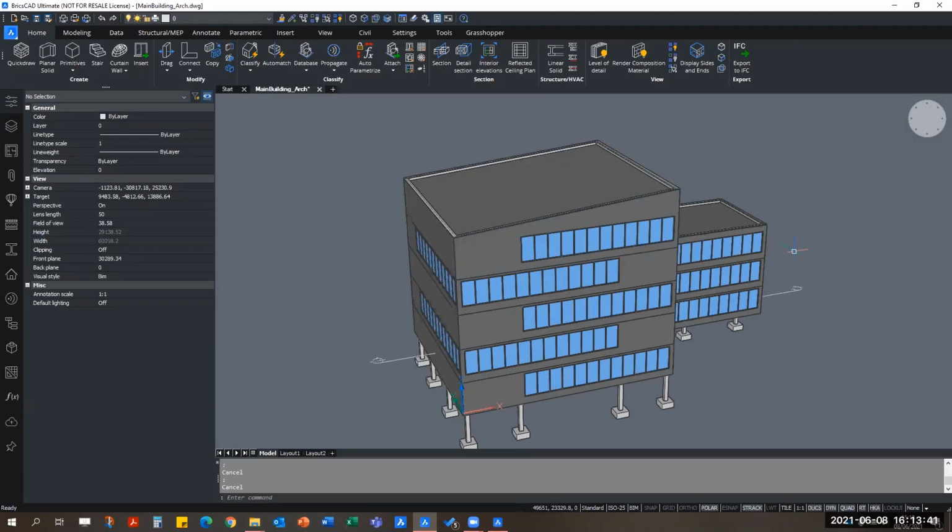Whilst this may not be the recommended or suggested move, to import your other consultants' drawings or models, because it can be against your local BIM mandates, etc. For example, in the UK, the BIM ownership is written quite clearly in the BIM mandate that you should only be able to XREF or link someone else's model and not touch their model. You can only touch whatever you've created as part of your ownership.